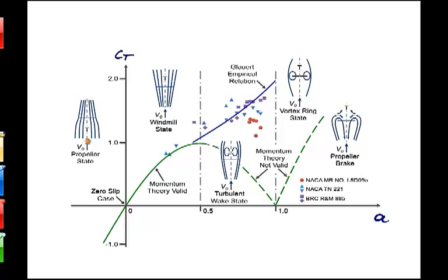And the thrust is really a thrust. The propeller is propelling us forward, while the wind turbine, in that case, the thrust is more of a drag, and it's pulling the rotor backwards and generating a large bending moment on the tower and foundation.